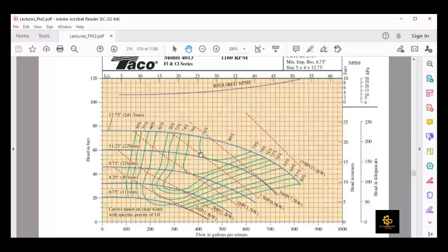First of all, we need to know the required volume flow rate through that pump in the piping system, and what the valid diameters are which are available, and then we can see where we can get the maximum efficiency. At which valid diameter would we get the maximum efficiency, right?